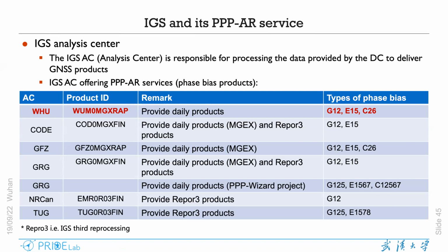Can one use the software for processing data from receivers that were not calibrated? No ANTEX input. You mean without any antenna calibration, so you can use the software to process that? If this is what you mean, for some low-cost receivers, because the antenna definition is not present in the ANTEX file, we can still process it, but the antenna offset and antenna phase center variations will be set to 0 in your final solution.